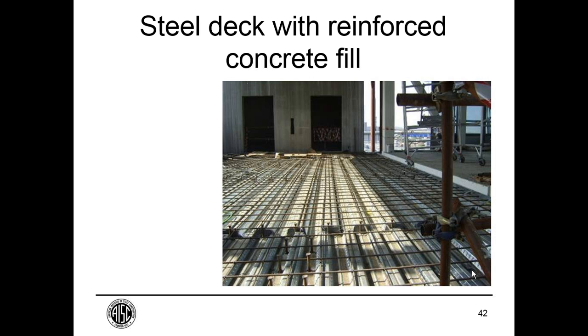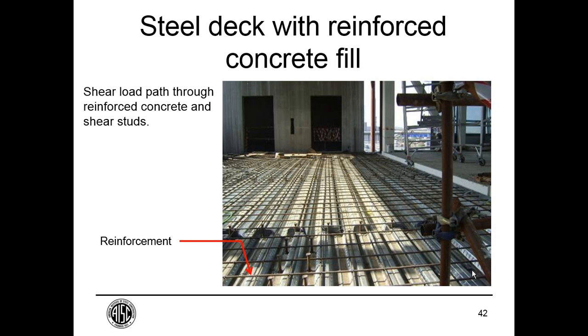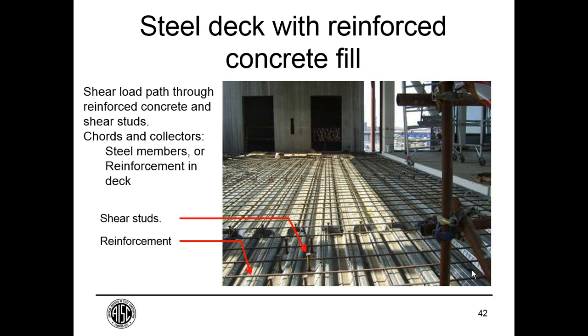When we have a reinforced composite deck, the shear typically we assume is in the reinforced deck, and in relatively simplistic terms, we might simply take the concrete above the top flute as a reinforced concrete member and calculate the shear strength of that. The transfer forces into members of our braced frame or moment frame may be through shear studs, and we may also use the steel framing as the chords and collectors, in which case we need to accumulate the forces through those studs into the chords and collectors as well. We could also use reinforcement in certain zones as the chords and collectors, and we'll talk about that a little bit later on in this section.